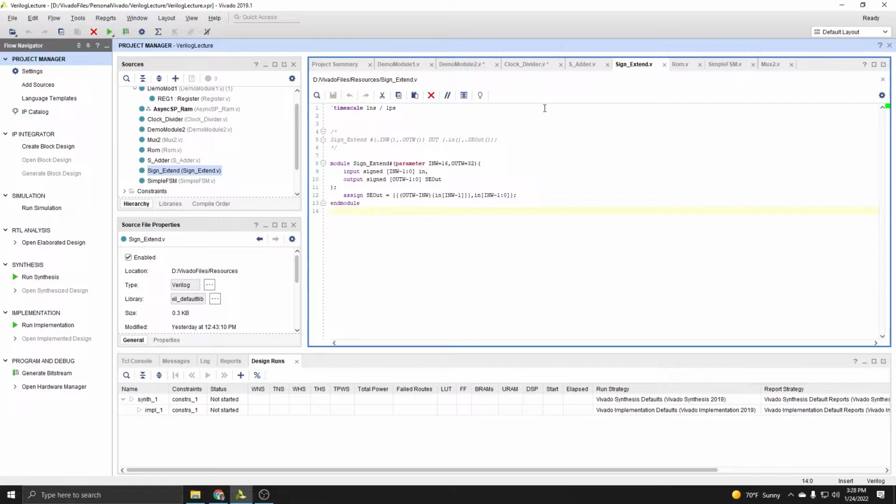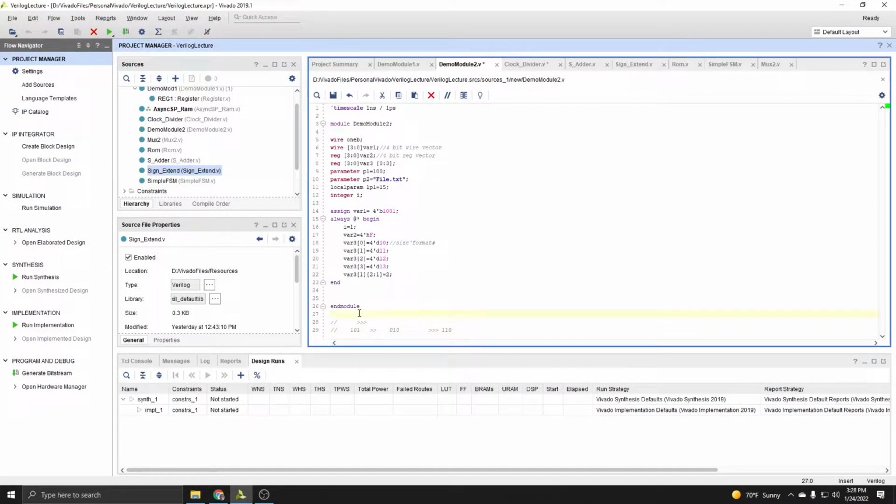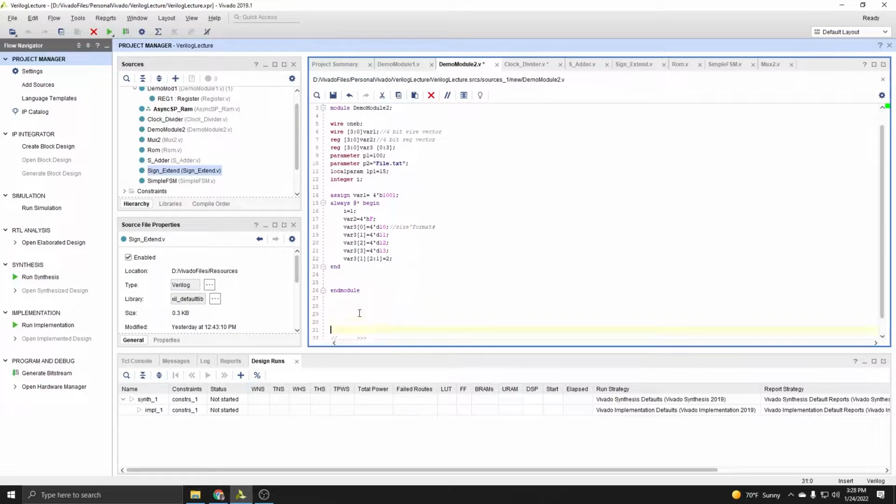Another thing that you can do that I'm going to go over here to show off as well, once again in comments down here, is you can use a similar concept of concatenation with the variable that you're assigning. So let's say you have two control variables. Let's say you have a write enable A and a write enable B and a write enable C for something.